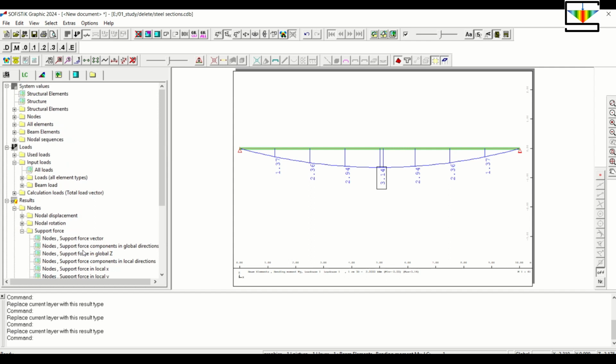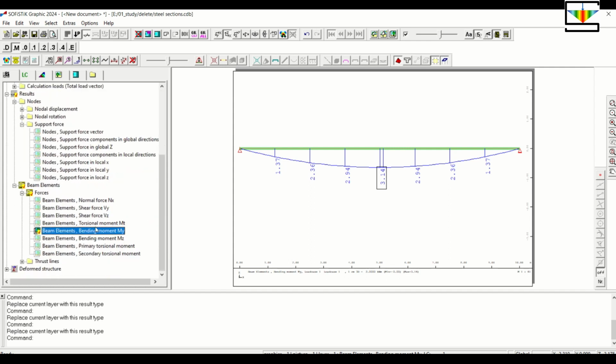There is no problem in the analysis even if there is a warning given by the program. That warning was actually for the shear, which will be considered during the design. We are just performing the analysis here and that's why there is no issue.